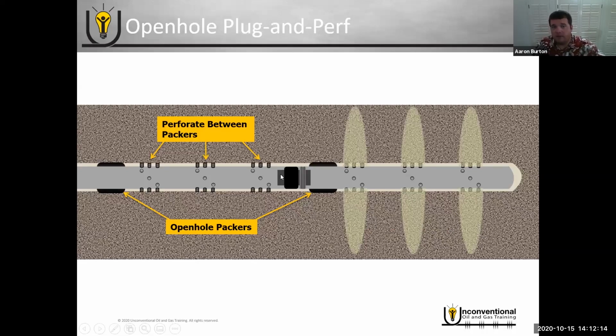The only difference is you're going to have to be sure that you place your perforations between the packers, because the open hole packers are now what's isolating rather than cement. So you don't have the full flexibility that you would have with cement. So you have to be sure that you place that plug and those perforations in the intended stage as you line them out with the open hole packers.